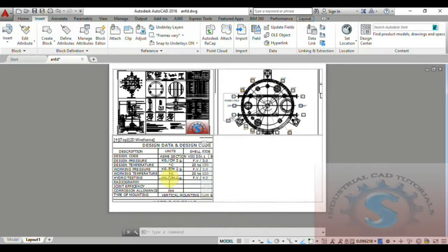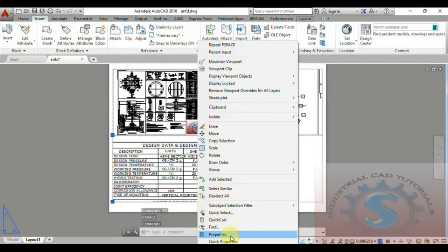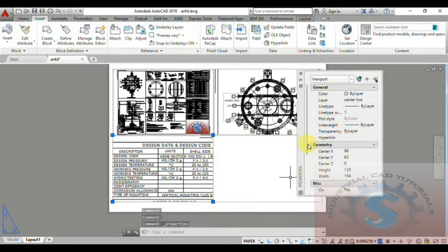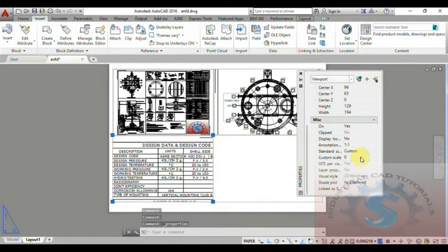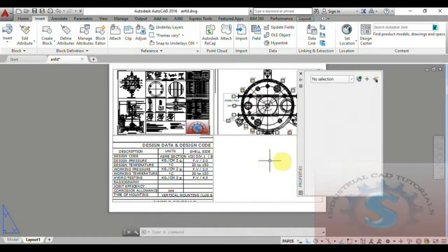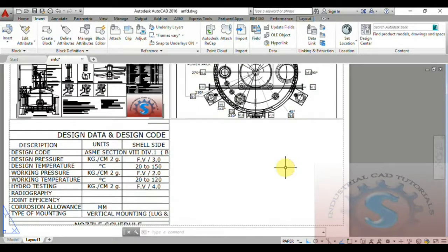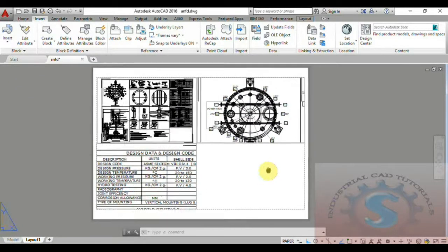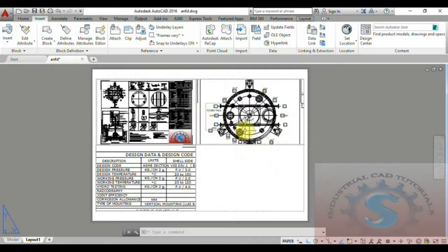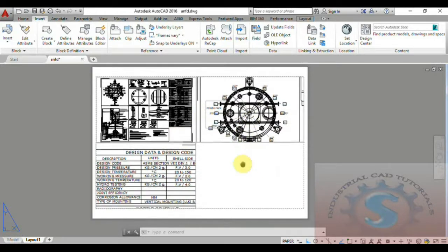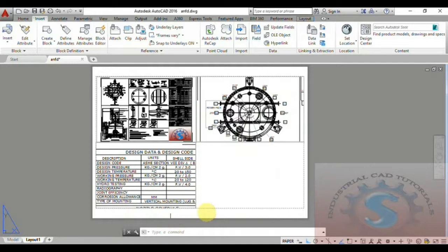You can place the different types of objects as compared with the millimeters, and PS enter. You can go outside from the drawing, go into the properties, the miscellaneous properties, and the custom scale, and you can also shade the layout and set the display locked as. If you want to keep the display location, you have to lock it. You can simply lock the display without editing, and by using Control P you can print the drawing to a PDF file. This is the MView. By using this the third is completed.